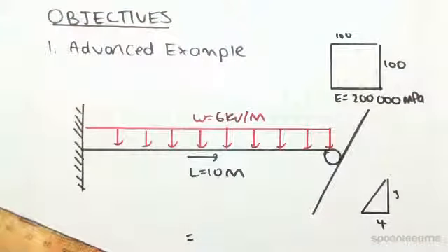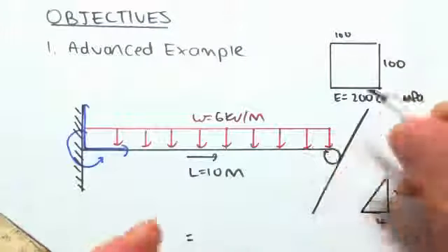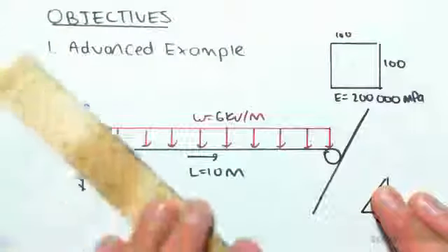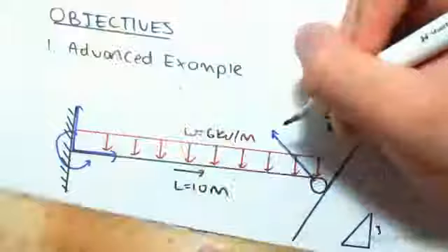Now, when you label your degrees of freedom, the global degrees of freedom are always in reference to your nodes. So what you're used to seeing is that, and that, and it might not be obvious why we're doing the frame element just now. You'll see why now. Because if this was flat, you would just do the beam element because you don't have any axial loading. But when you label this node here, the degrees of freedom, it looks like this.